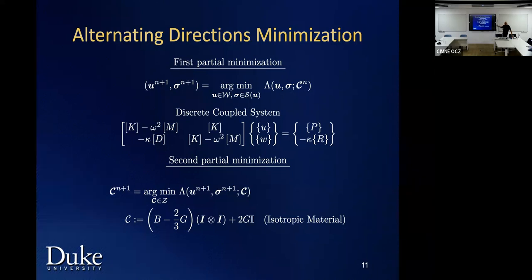This is the way that we implemented this originally. If you have ever studied alternating directions solutions, this is similar to Jacobi type of applications, right? In nonlinear systems, they can diverge easily, okay? So now the optimization approach where you use trust region line search is very robust. That's the way I solve everything these days.